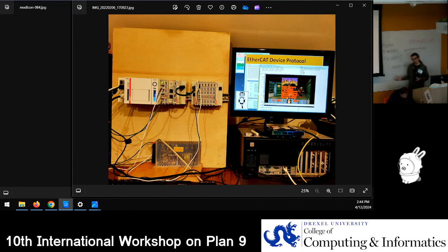So I have a very small little listener that listens for Modbus frames, and as they come in, they're processed. What I wound up doing was mapping out the file to where you would say where your registers live, where your bits live, and if they overlap or not. And from there, it returns the data from that file as if you're looking at PLC registers or bits inside of it.